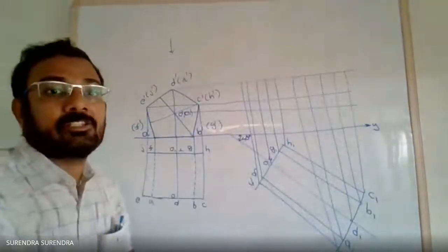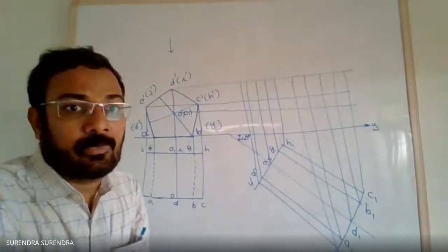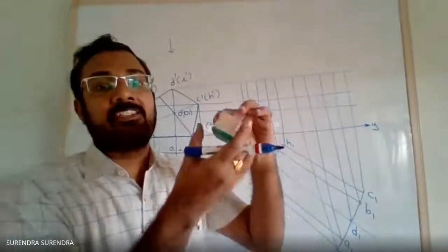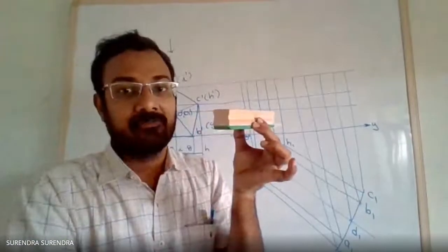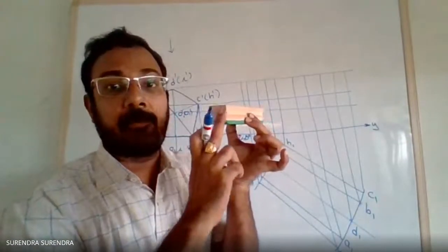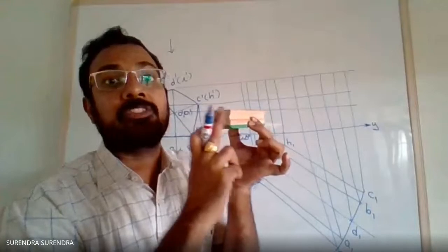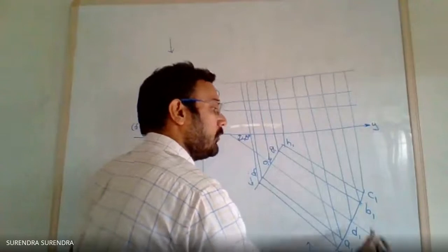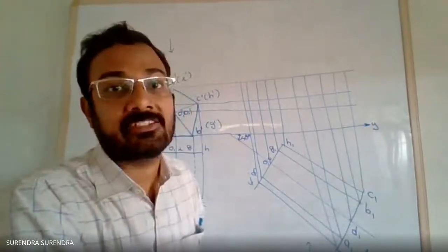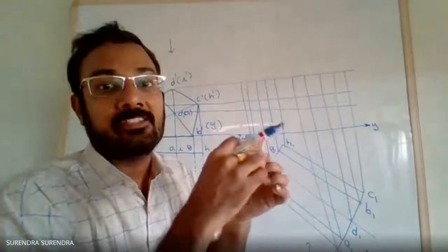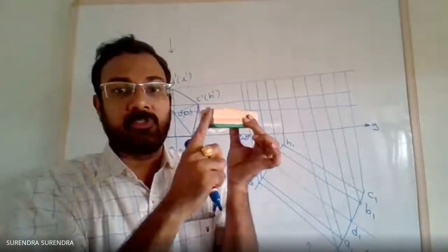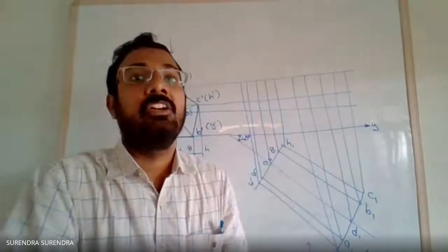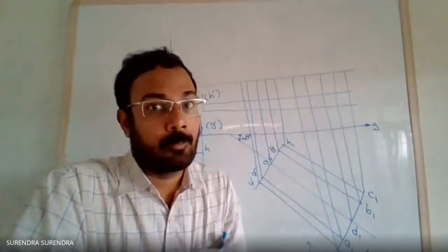Now, mark the respective intersection points first. Mark the respective intersection points, top base and bottom base. When the axis is inclined at 40 degrees, you can see the complete base, the base which is nearer to the observer. So, as we are seeing in this direction, you can see the A, B, C, D, E base completely, E, F, G, H base. See here, one complete base. What about the second base? Only one or two edges, depending on its orientation and their position.